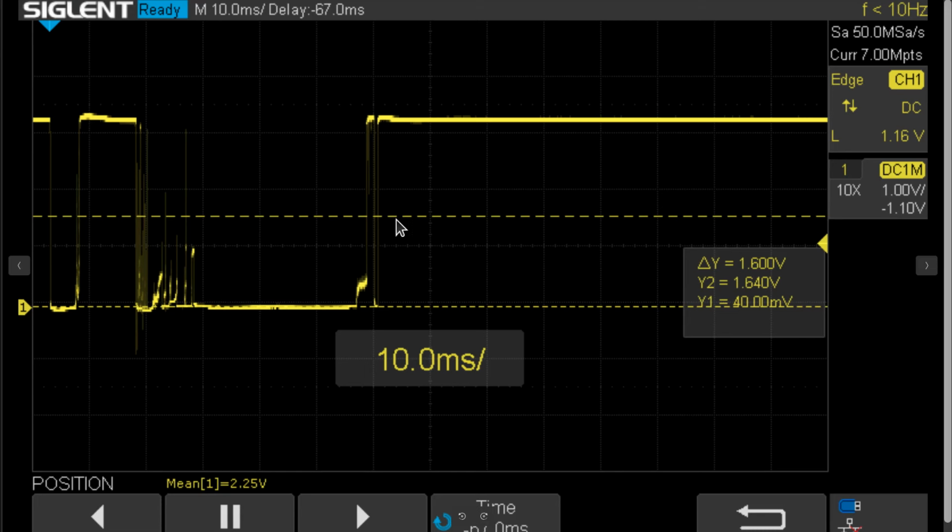But in a normal case, you've got these little glitches that look like this. We need to pick a time. Now, this one's tough. This really is tough, because it went down, stayed really clean, low, and then it went up and stayed clean, high. Unless you set it to like 15 milliseconds, which is reasonable, I suppose, you can't ignore this thing because it lasted too long. There'll always be one just a little bit longer, right? But this is how you decide what you want to do. It really depends on the switch you chose, the voltages, all your circuits, and whether your user has some serious problems when it comes to pressing buttons or not.